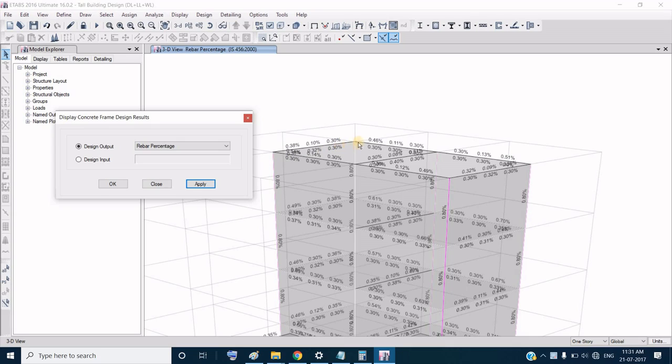So you can very easily identify whether the minimum reinforcement has been passed or not. And the maximum reinforcement in the column, though the code recommends 6%, it is recommended that 6% is very high for a column. You can go for 4%, which is sufficient. You can check very easily that 0.8 is the minimum value given here.